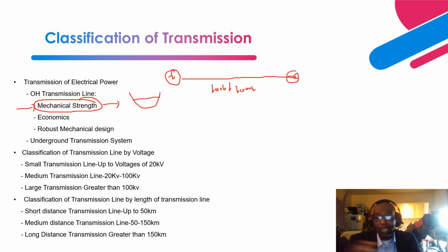Excessive ice or snow falling on the lines can, with its weight, cause these phase conductors to sag, right? And if it sags, it can create other problems, right? Also, if you have excessive rain, it can cause short circuit in between the phases.